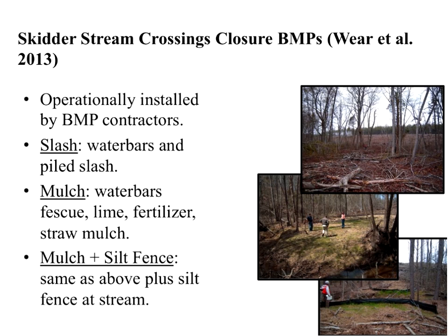This was a study that Laura Ware did, looking at skid trail stream crossings and closure techniques. We used the same crossings that we talked about earlier, where we had slash versus mulch. We're putting down water bars combined with fescue, lime, fertilizer, straw mulch, and then the mulch and silt fence is the same as the mulch plus silt fence.